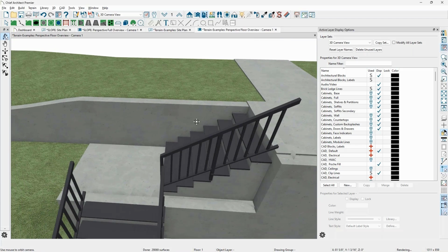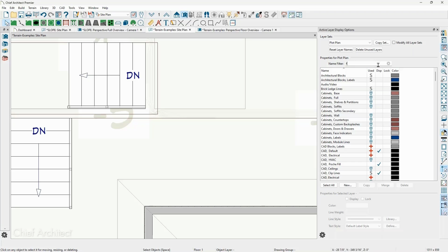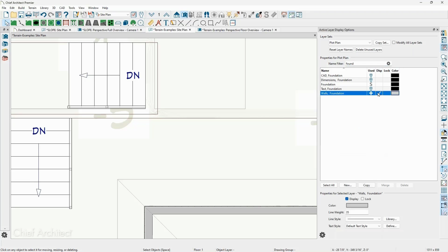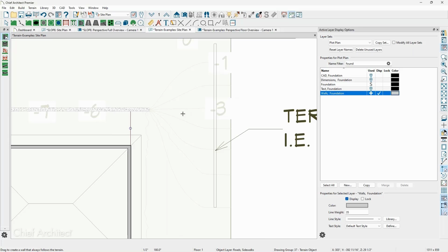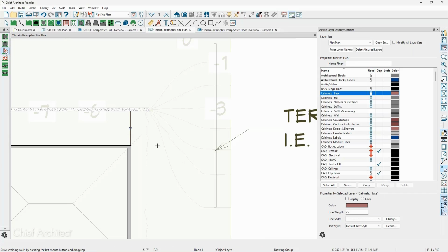Yep, exactly. The way that works when you are in the terrain itself, let's turn those foundation walls back on that we were just working with, so you can see these. This is considered a retaining wall. As I've moved my toolbar over to the terrain configuration, that tool is right here. It's called terrain wall. You can see there is a straight retaining terrain wall, which will follow the slope. And then the other one is a retaining wall, which will retain and break the terrain. So when you use this and we break the terrain, I'll just draw another, let's make sure I use the right tool here. I use this retaining wall, we break the terrain in here, and we regenerate the terrain.